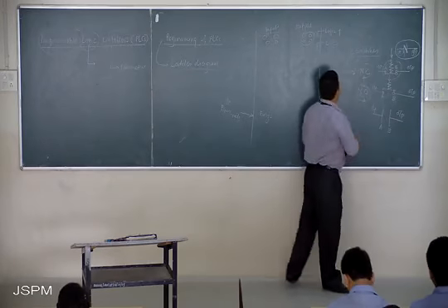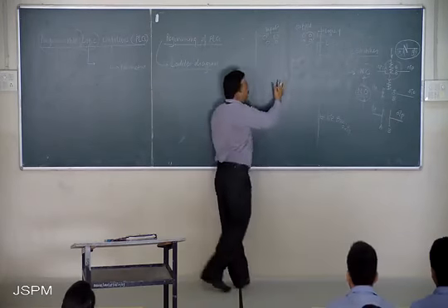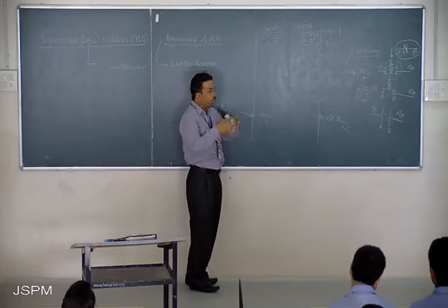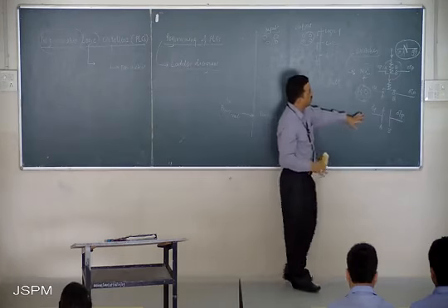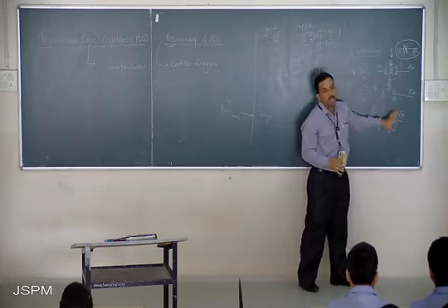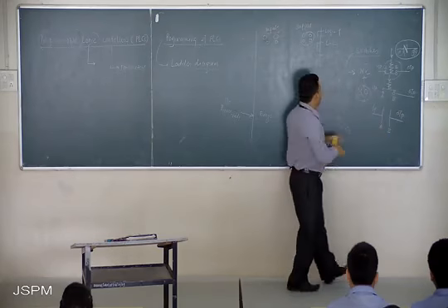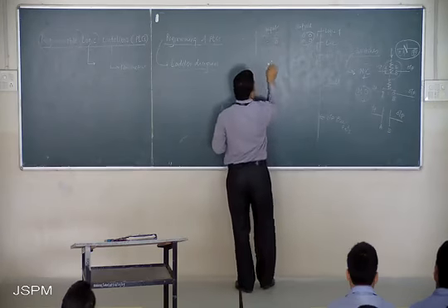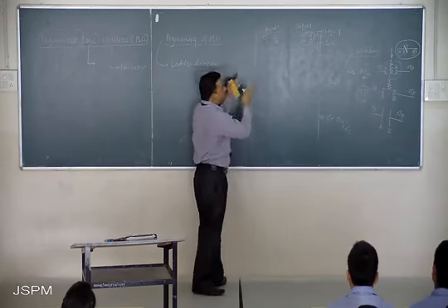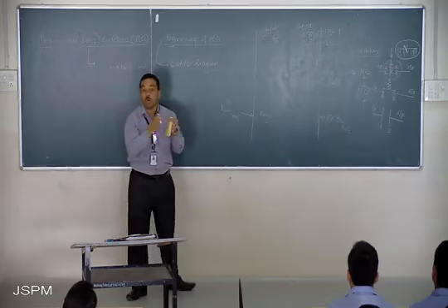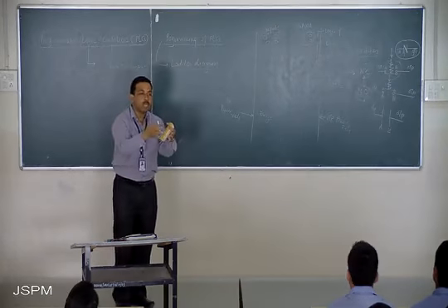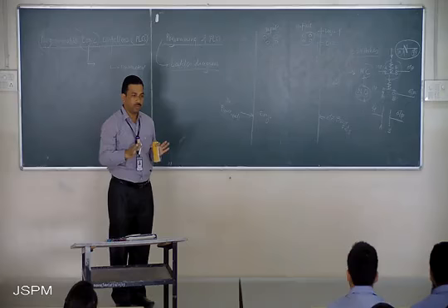If you look at any ladder diagram, you will find a combination of these types of switches, either normally closed or normally open. This region, which is nothing but the inputs region, is full of combinations of NC and NO, based upon the logic that you want to incorporate.